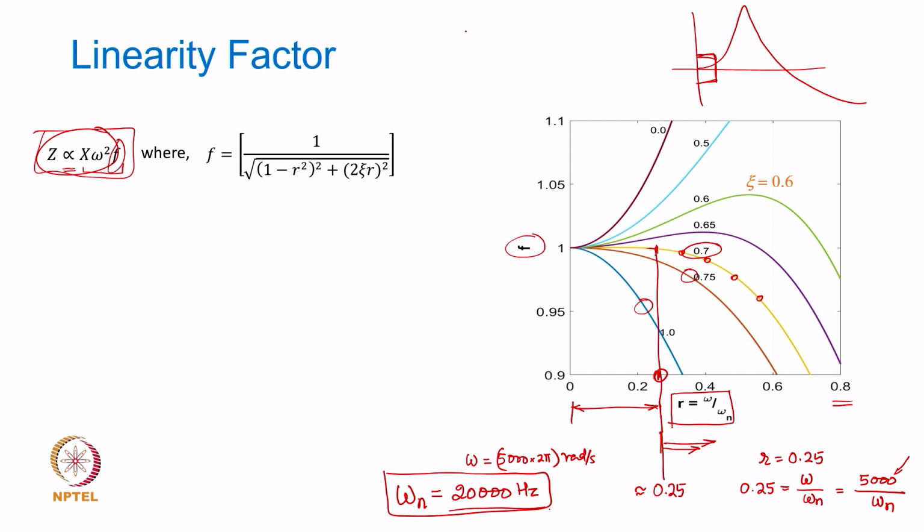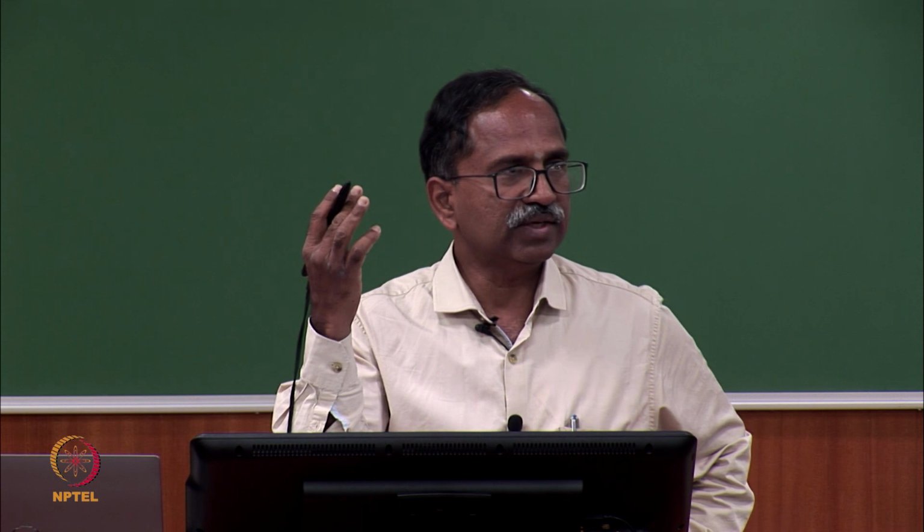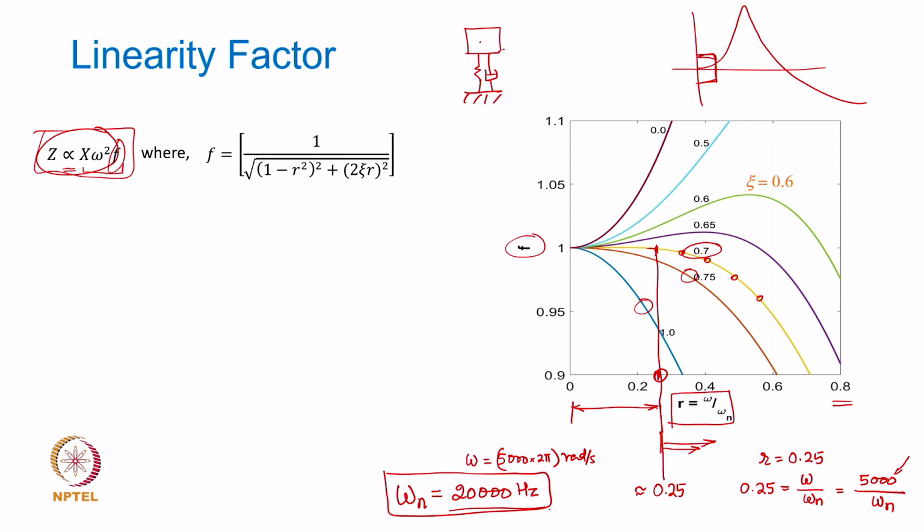So, if I am modeling this accelerometer as a simple spring mass dashpot system, then you know that in that small size accelerometer the mass can't be large, right, the way we have in a seismometer. Okay. So, the mass is not too large, so the mass is limited, and for a natural frequency of the order of 20,000 hertz, and maybe if you want to convert this into radians per second, it is going to be even further larger value, right. Such a large natural frequency means what?